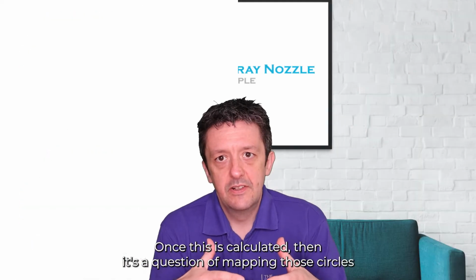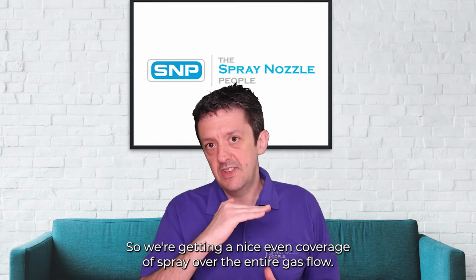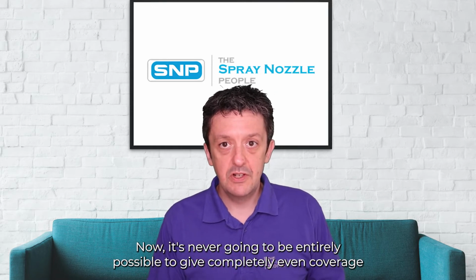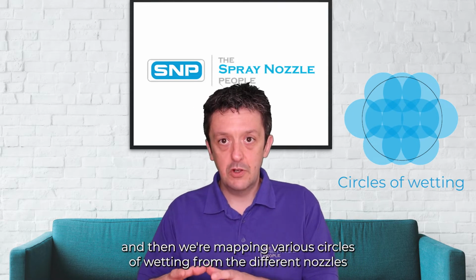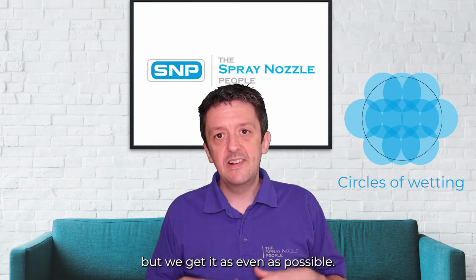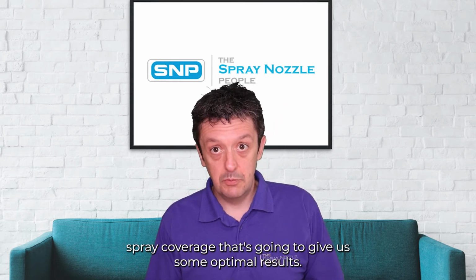Once this is calculated, then it's a question of mapping those circles onto the overall geometry of the gas flow, the geometry of the chamber, so we're getting a nice even coverage of spray over the entire gas flow. Now, it's never going to be entirely possible to give completely even coverage, because if you imagine we've got, say, a circular scrubbing chamber and we're mapping various circles of wetting from the different nozzles onto that, we're never going to get completely even coverage. We're going to have some overlap, especially around the edges, but we get it as even as possible, and that's going to give us an idealized spray coverage that's going to give us some optimal results.